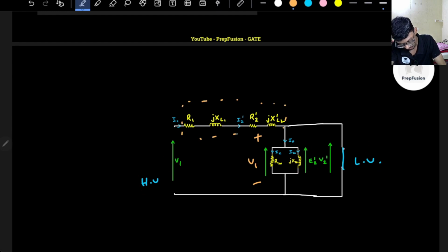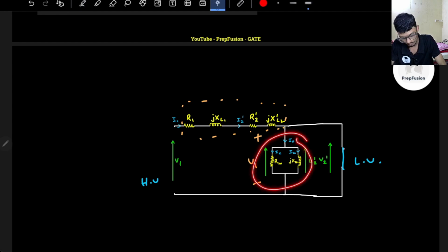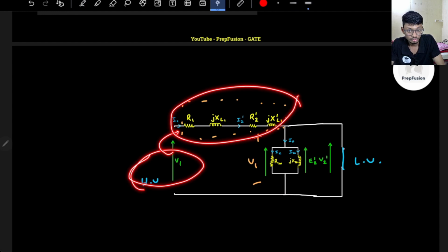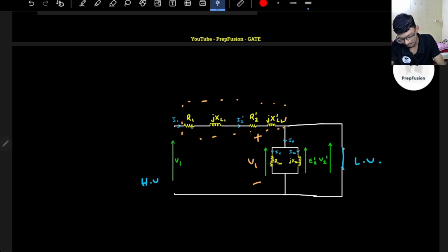That's it. Because here the induced voltage is 0 only, right? So the voltage that I need to supply is only this amount of voltage. So that's a good thing. That's why we short it basically. That is the reason we short it. Because for full load copper loss, mainly what is important? The current should be full load. Voltage they have not shared any condition.